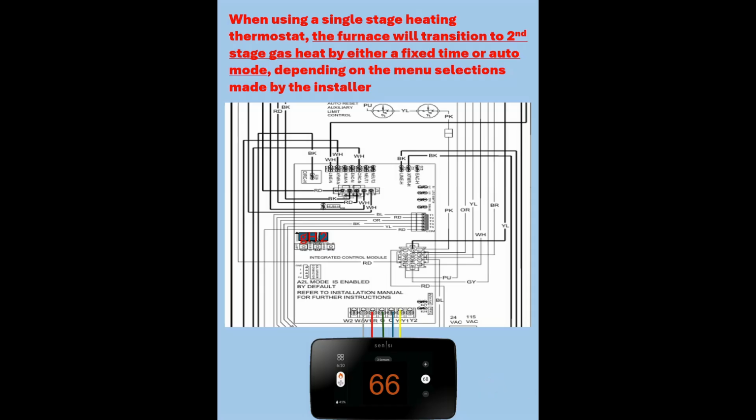When using a single stage heating thermostat, the furnace will transition to second stage gas heat by either a fixed time or auto mode, depending on the menu selections made by the installer. So just remember that. If I was in the field, I have one of these. I have the previous generation of this.